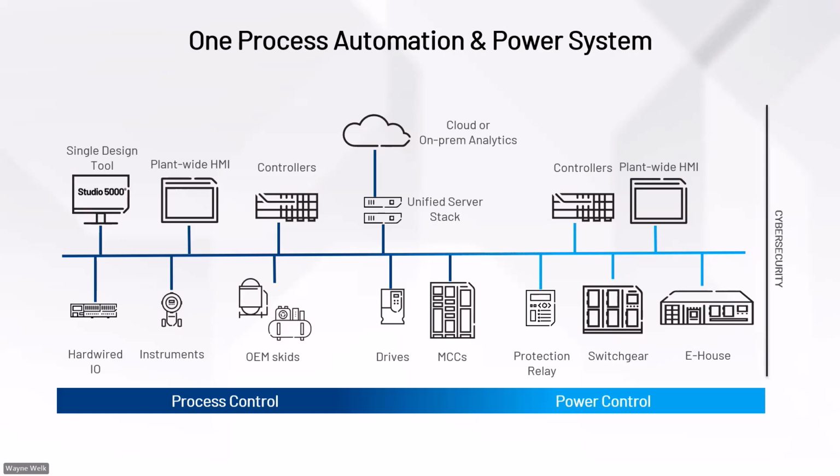So traditionally, a lot of the electrical devices have been hardwired to the process control system. So typically, you may see a trip in your process control system, but you have a limited amount of information about troubleshooting that trip. In an intelligent power system, because it's networked together, you have much more actionable, detailed information available to you. Not only what tripped, but what device it is, and what electrical device is associated with it.